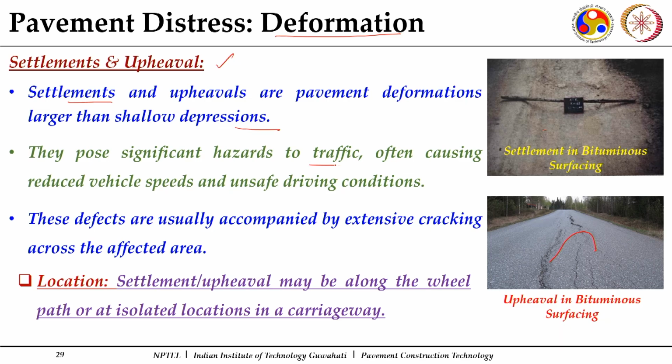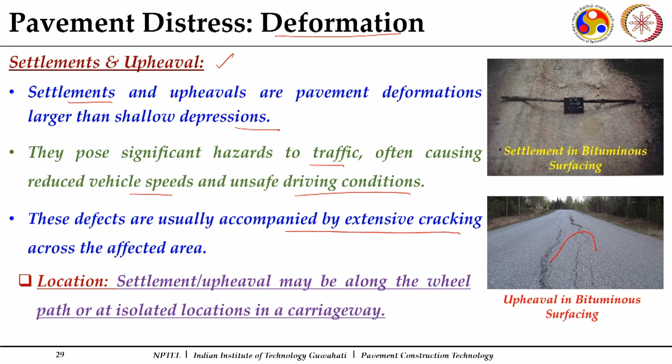They pose a significant hazard to traffic, often causing reduced vehicle speeds, unsafe driving conditions, and cracks also get associated with these settlements and upheavals. So, these defects are usually accompanied by extensive cracking along the affected area. They further allow the water to go into the underlying layers. Settlement or upheaval may be along the wheel path or at isolated locations in a carriageway.